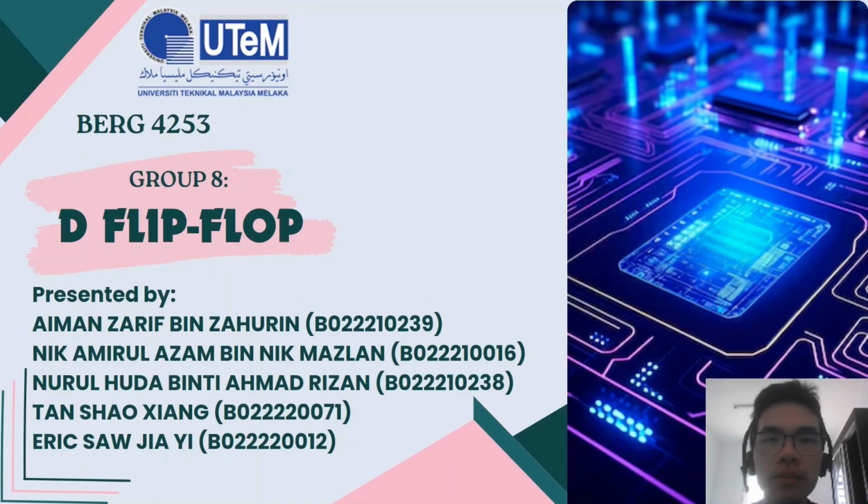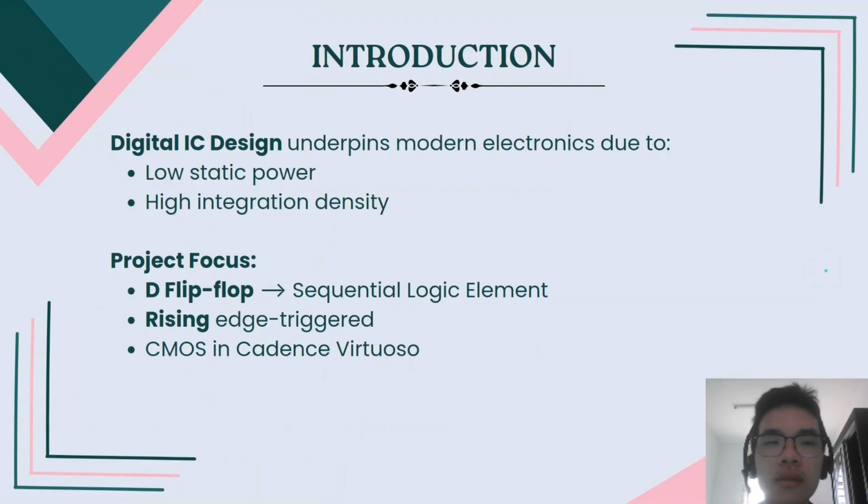Hi, we will be presenting our project on the CMOS implementation of a flip-flop using Cadence Virtuoso. Digital IC design underpins much of today's technology. We rely on CMOS because it provides low static power consumption and high integration density, which are crucial for compact and efficient electronics.